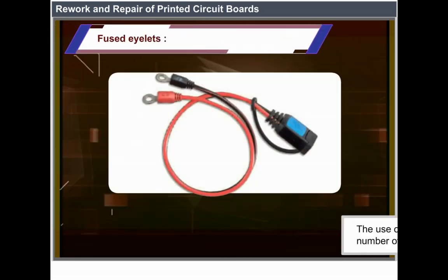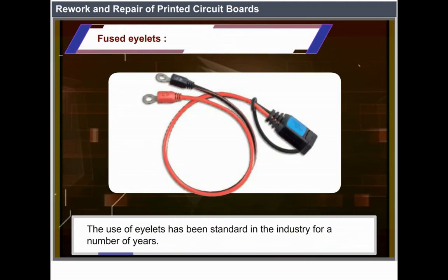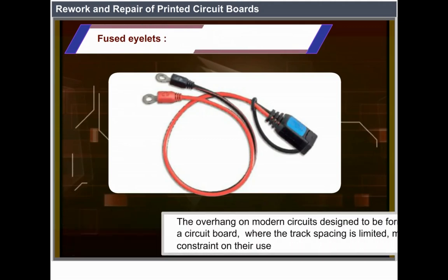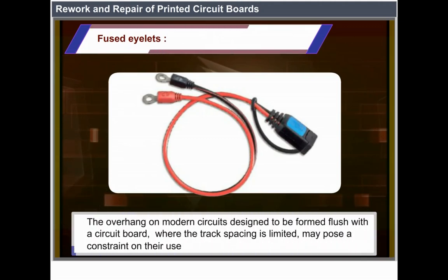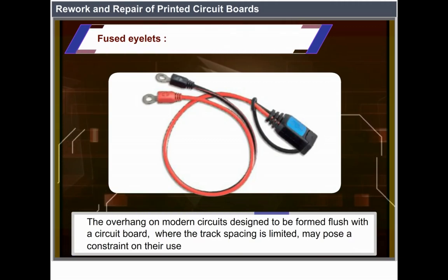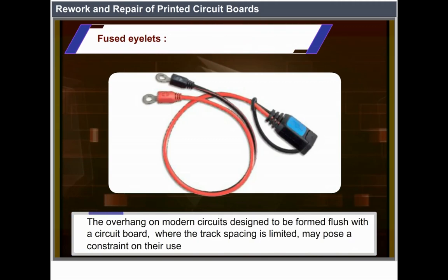Fused eyelets. The use of eyelets has been standard in the industry for a number of years. Designed to be formed flush with the circuit board, they overhang on modern circuits where the track spacing is limited. This may pose a constraint on their use.